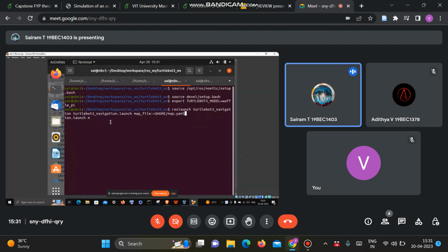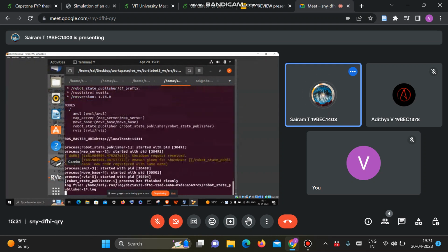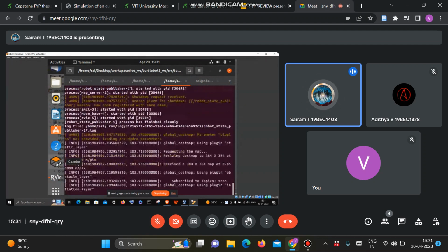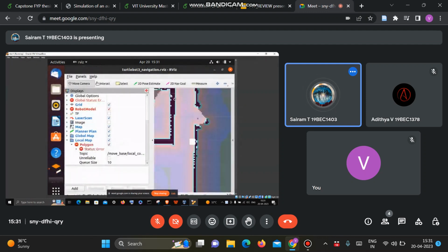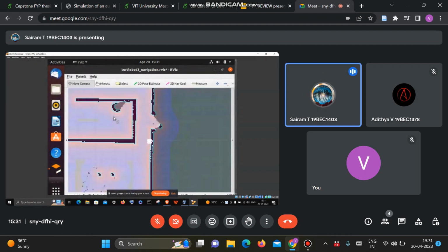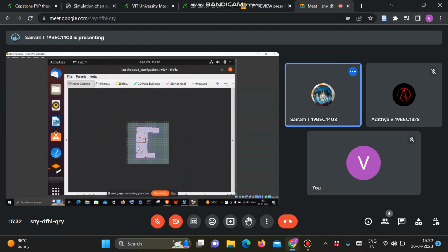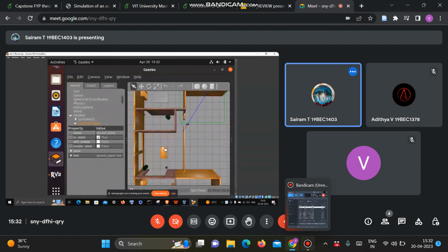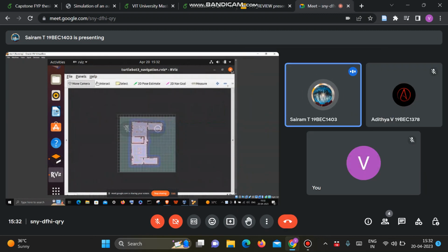The A-star algorithm path plans for every few meters or centimeters of distance. After that, it updates the path planning, and for minor adaptations, the AMCL will take over and adapt for the optimal path. Since the map generated by SLAM won't be perfect, as you can see here, the map is distorted somewhat compared to the world. So we are using the hybrid version that will mostly optimize the path.